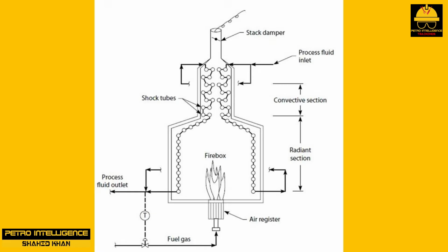This is because more heat is given to the process fluid and less heat goes up the stack. 2. The heater process outlet temperature declines as airflow is reduced past the point of absolute combustion as defined in the next section. In this situation we have products of incomplete or partial combustion, such as aldehydes, ketones, and carbon monoxide going up the stack.